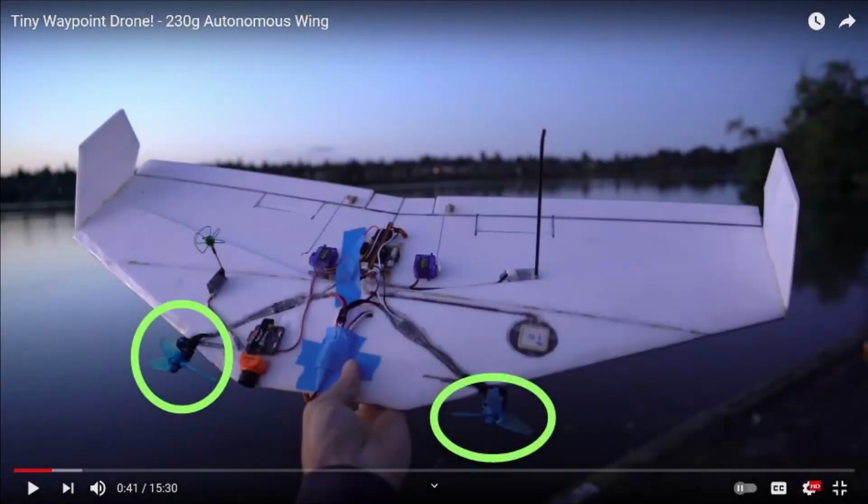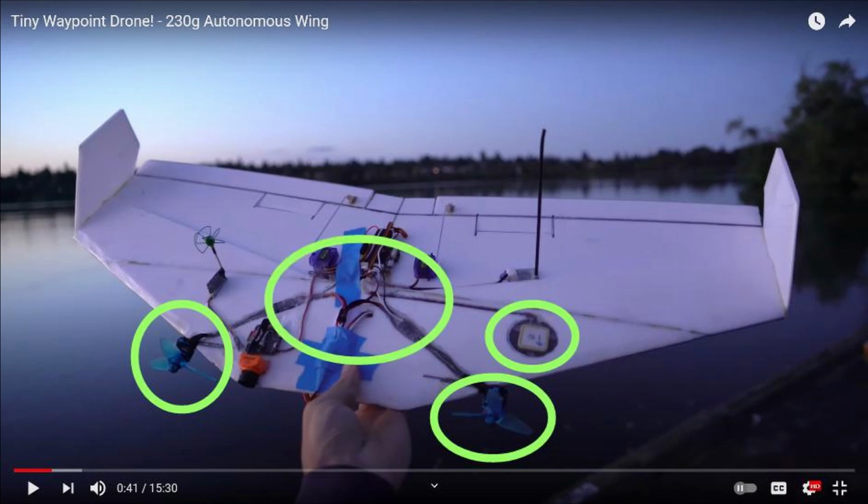First off, he uses differential thrust for yaw, which doubles the prop, motor mount, and ESC masses. Second, he uses a pretty chunky GPS receiver. And third, there's a lot of excess wire on the aircraft. And the biggest knob we have to turn is that we can probably get away with less wing. And so with meticulous attention to weight, I think that puts us right in the gray area between possible and impossible, and that's my favorite place to be in engineering projects.